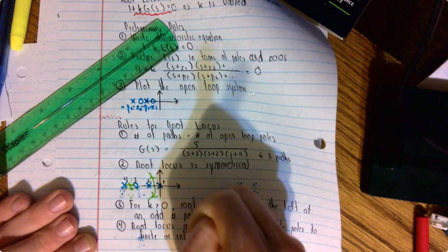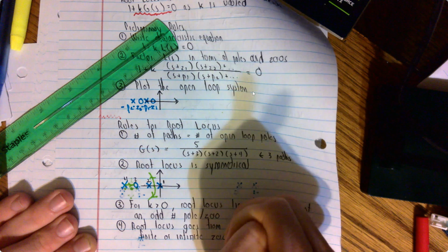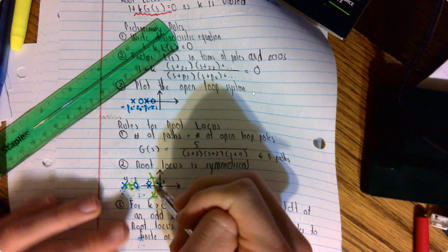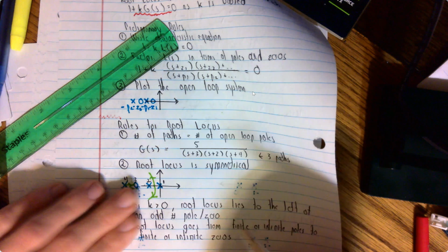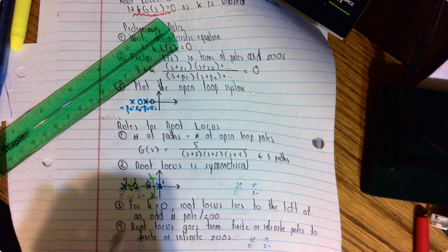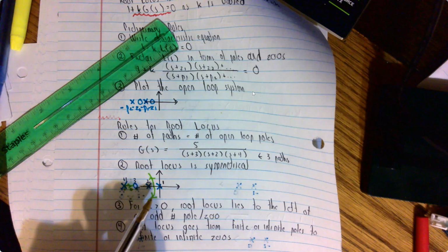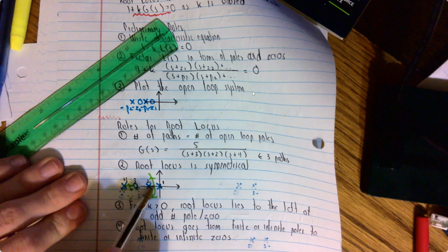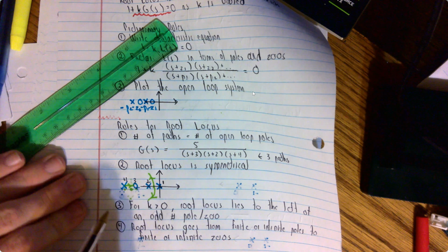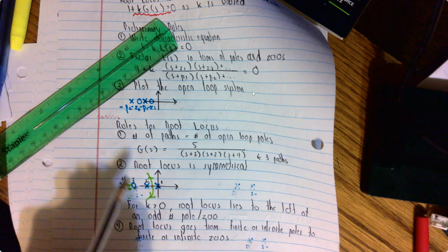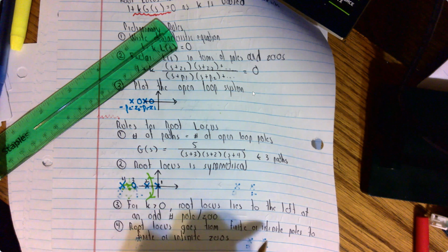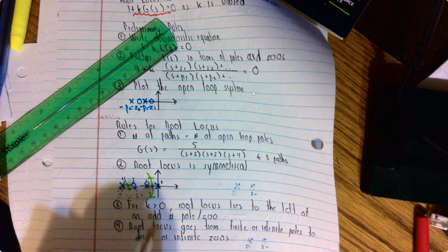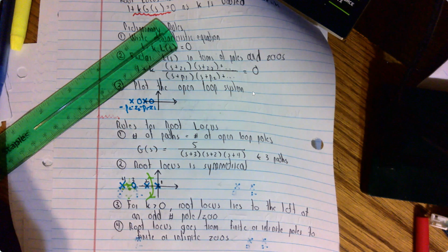This is just basically saying that up here, notice that it went from a pole to a 0, and there's only one 0, so the other two poles went to infinity because there wasn't any other zeros. So it's basically using like a higher order system. If you approximate it, remember those zeros would be so far away that they didn't have any effect. But basically what it's showing you is that it goes from poles to zeros, and then if there's no more zeros, it goes to infinity.